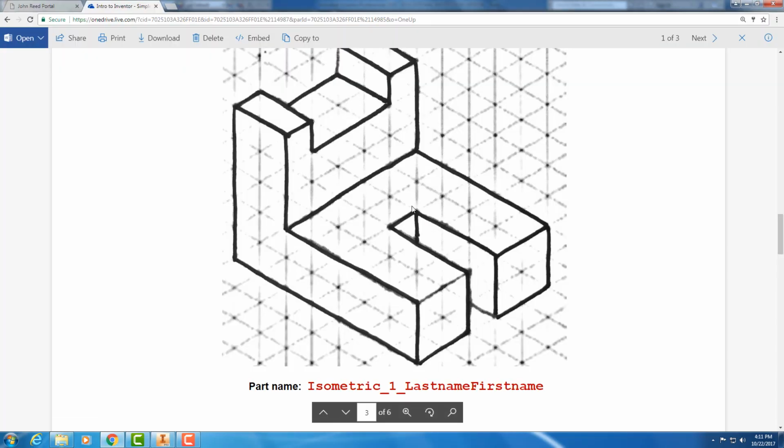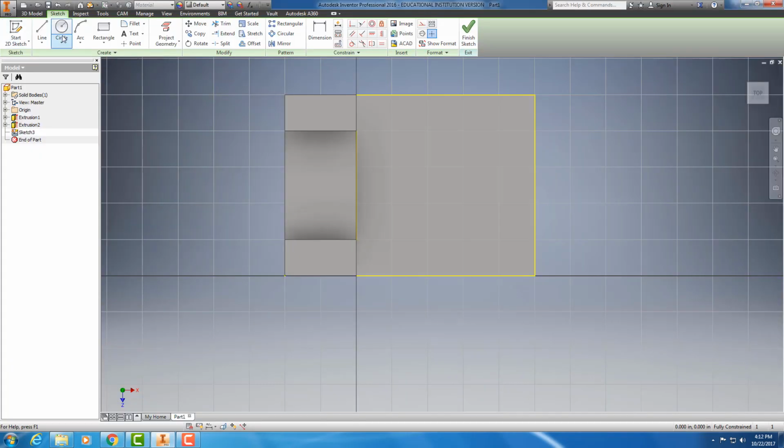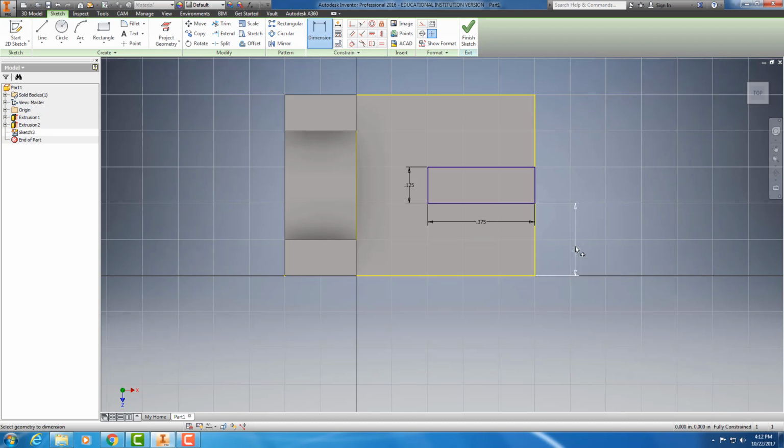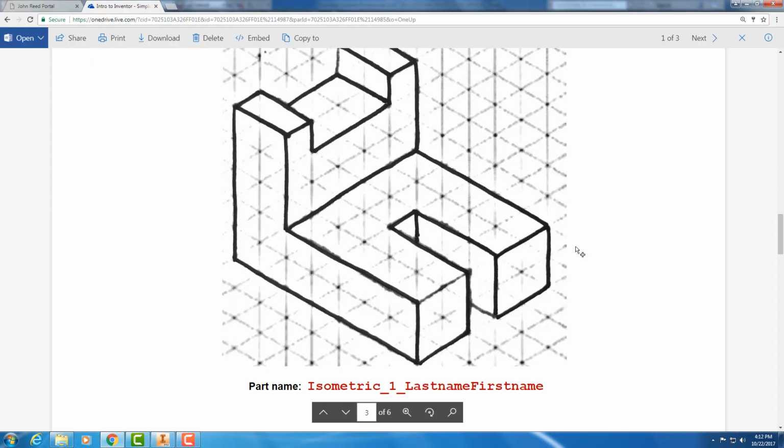And basically, I need to make this little rectangle here, and it's centered here, and it goes back 3 units, so it's 1 by 3. So rectangle, let's attach it there, and this is lengthwise, it's going to be 3 times 0.125, tab, 1 times 0.125, enter. Okay, I think the dimensions of that rectangle that I'm going to extrude are correct. Now I need to locate it. So from here to here, I know that I need to go, what was it? I believe it was 2 times 2 squares, 2 times 0.125. And that's fully constrained. Yep.